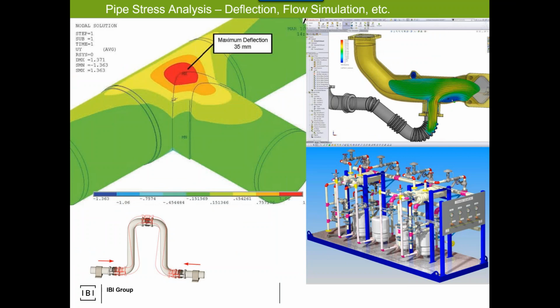Pipe stress analysis. Here's an awesome one. We're defining a technical solution. I, the piping designer, want to analyze my pipe stress. Right away, that's just a trigger saying, okay, I need a plant-based BIM authoring tool. Pipe stress analysis, P&ID integration are two triggers to say, get away from building and civil and find plant. How this works is it allows me to define my workflow, my material, probably whether it's pressurized versus not pressurized, and then allows me to analyze and adjust accordingly.